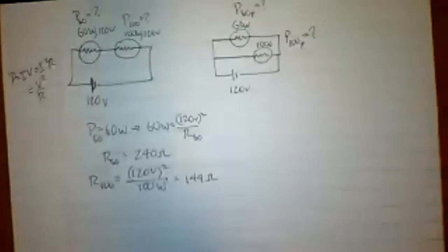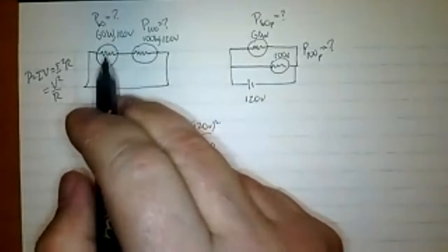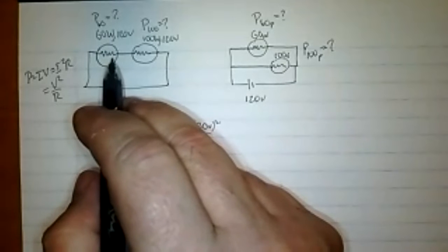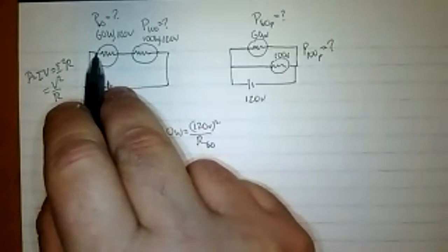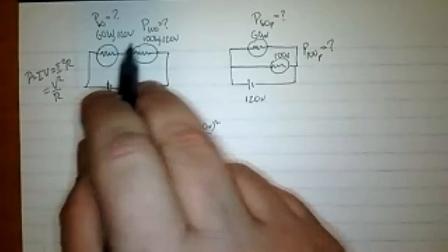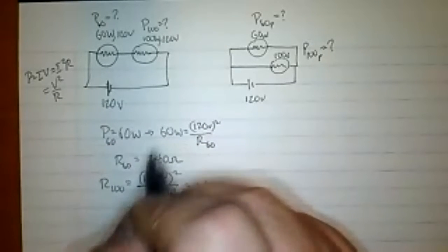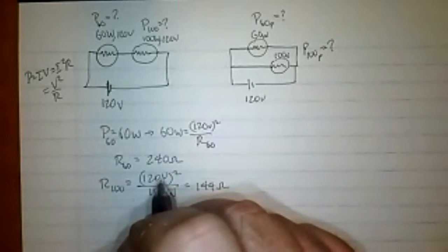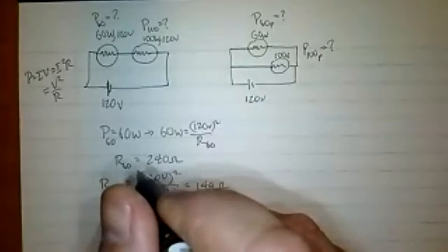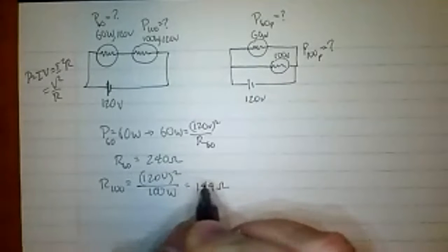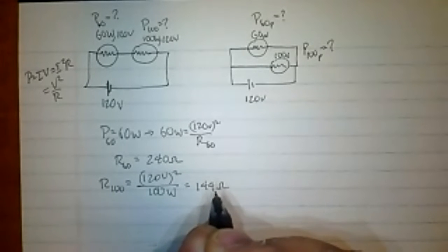So now we've got the resistances, and we're going to ignore, when I put it here, this is really not going to be 120 volts across that resistance, right? Across that light bulb, because now I'm taking the 120 and part of it's going to go across here and part of it's going to go across here to add up to give you 120. But I'm going to pretend like that resistance is roughly the same in all of these configurations. So that's a big assumption. It might not be that correct, but it's a first order approximation to trying to get the right answer.